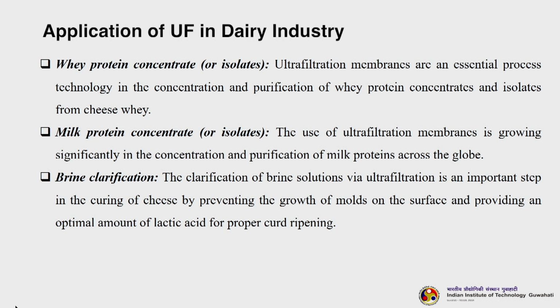So, many things happen in the dairy industry, different processes. So, we will discuss a few. So, the first one is the whey protein concentrate or isolates. Now, ultrafiltration membranes are an essential process technology in the concentration and purification of whey protein concentrate and isolates from cheese whey. Second is milk protein concentrate or isolates. So, the use of ultrafiltration membrane is growing significantly in the concentration and purification of milk protein across the globe.